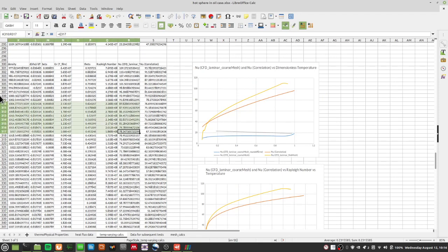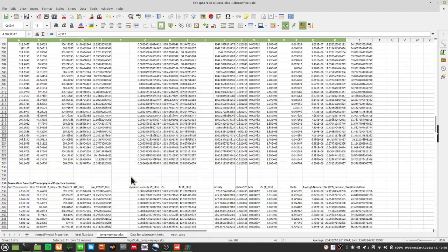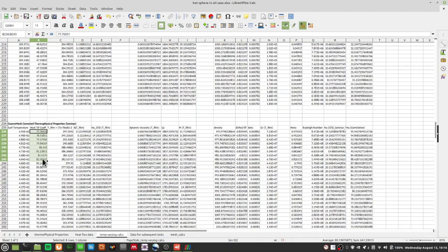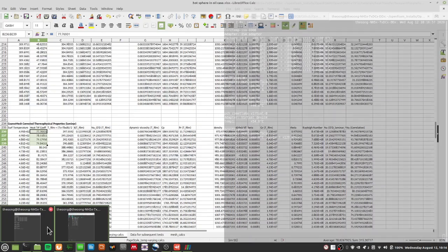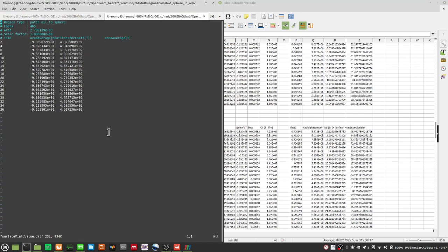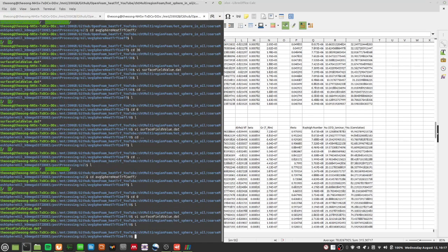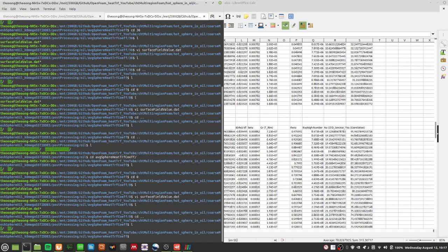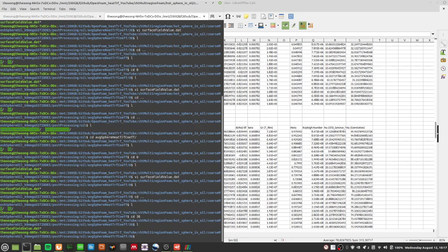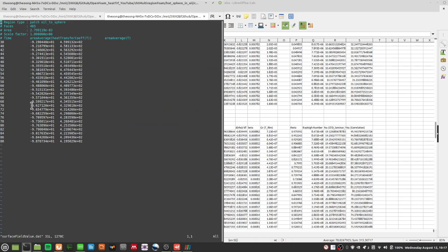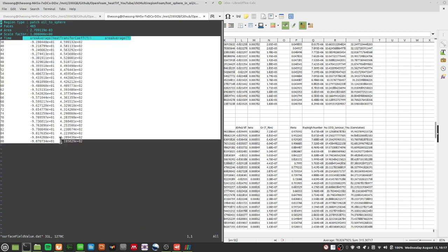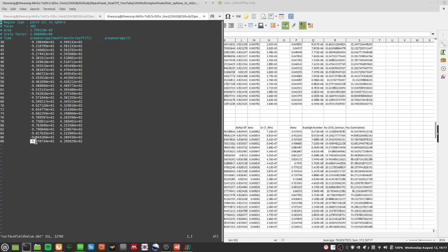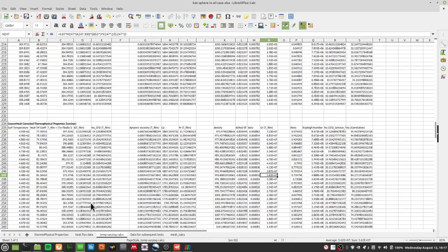If we just do a comparison with the coarse mesh, we see that the heat transfer coefficient increases quite a bit compared to the coarse mesh, but it's not as accurate as having a fine mesh. You can see the heat transfer coefficient is increasing. Sometimes, like at 88 seconds, it is about 98 watts per meter squared per Kelvin.